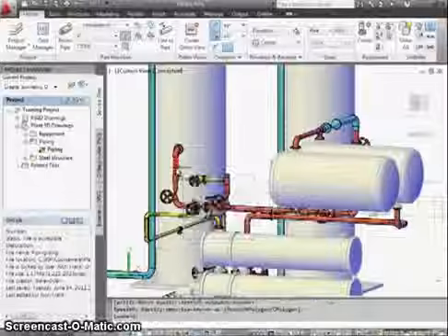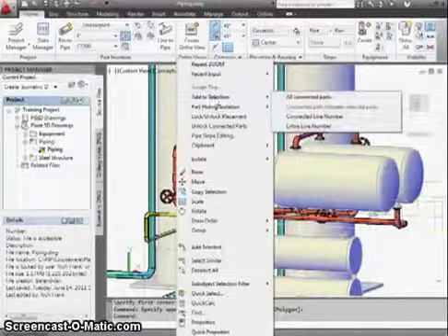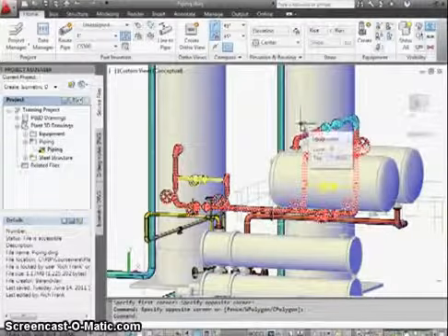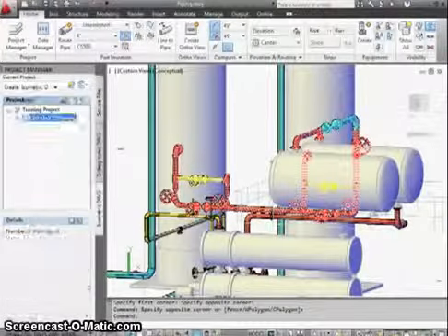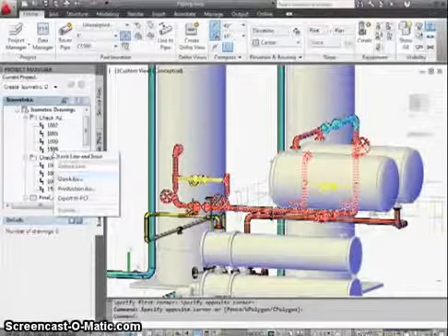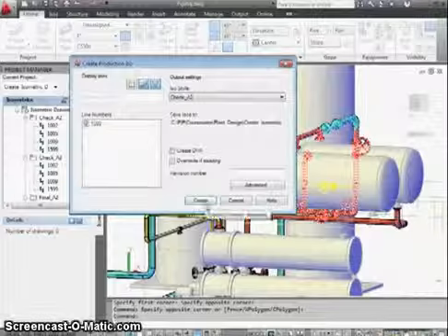Create a quick ISO based on a drawing selection, but when you create quick ISO drawings, they're not added to the project. So instead, we're going to create a production isometric. In the Isometric DWG tab of Project Setup, for the ISO style check A2, we select the line number 1599 and then create a production ISO.